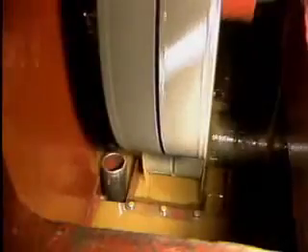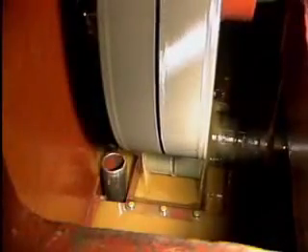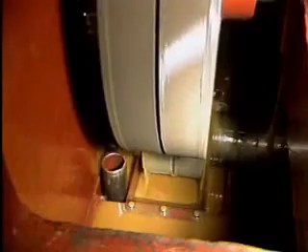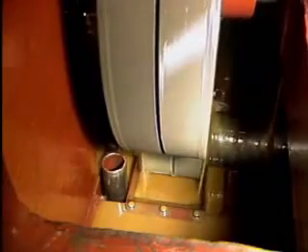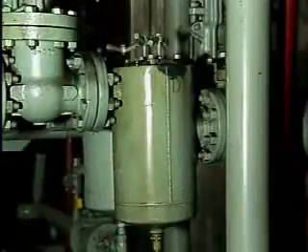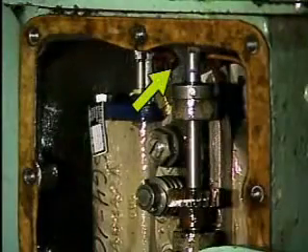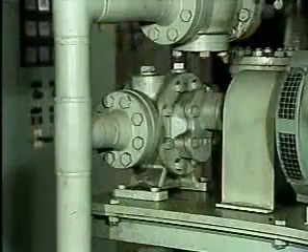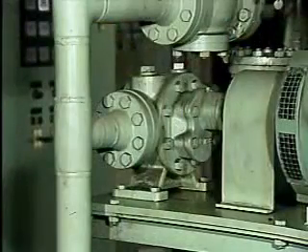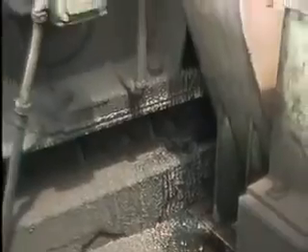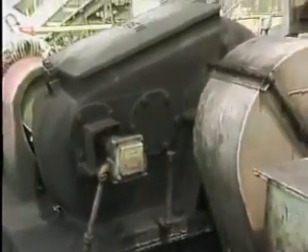If a lubricating system does not lubricate all of the gear's tooth surface before they mesh, overheating and excessive wear may occur. Insufficient lubrication can be a result of clogged filters, clogged or improperly adjusted spray nozzles, or the improper operation of the lubricating system. Also, lubricant can be lost from a gearbox through a blown seal or a leaking joint. As you might guess, a problem that develops in a gear set's lubrication system may end up damaging the gears.